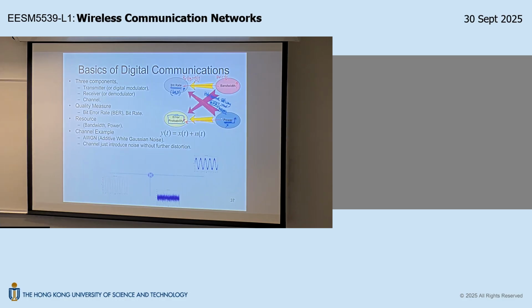However, in 3G, 4G, 5G cellular networks, you seldom come across a modulation of 4096. The highest constellation I come across is something like 64. For 3G it is 64. For 4G, I forgot, it is something around 64 QAM. Definitely there won't be 4096 QAM in a cellular network. Why not?